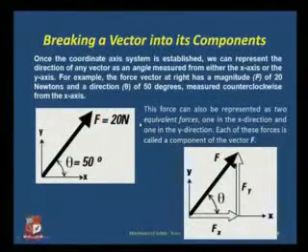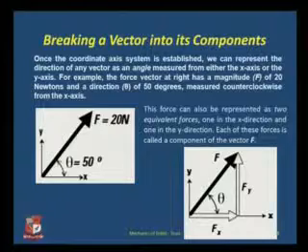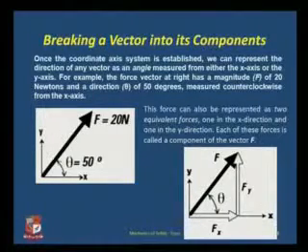Now we have looked into the length part. Now if I want to find out the components of a vector, which we will actually be doing when we are solving a truss, then I have to look into two things: the magnitude of the vector and the direction of the vector. Here I am considering that the direction of the vector is with respect to the positive x-axis, going in the anti-clockwise direction. You can take the clockwise direction, or with respect to the y-axis, negative x-axis, positive x-axis, negative y-axis or positive y-axis. Either way, you have to look into the same phenomena that I am teaching you here.